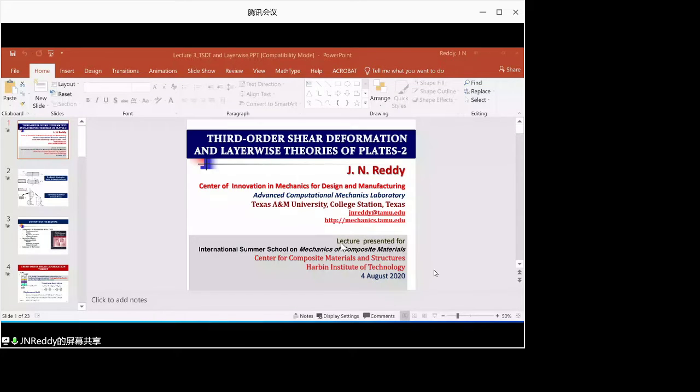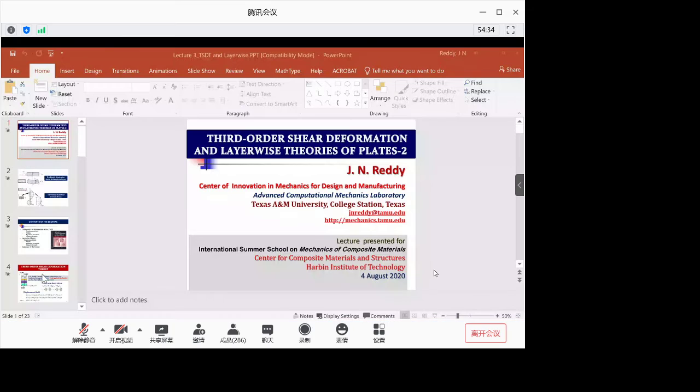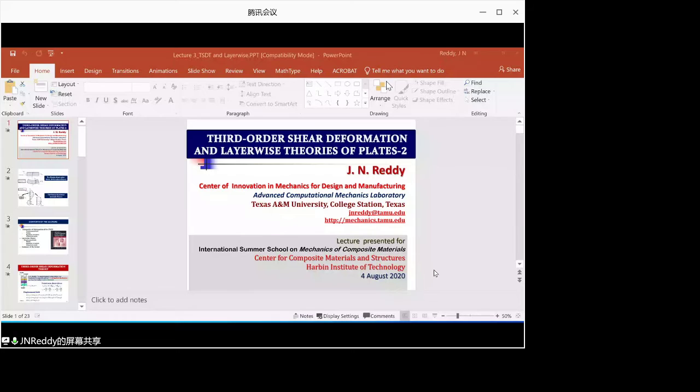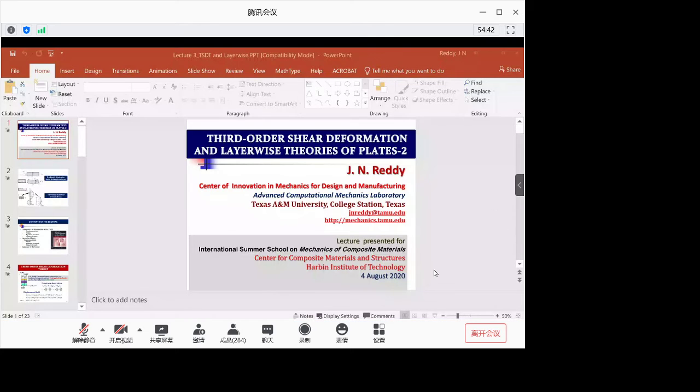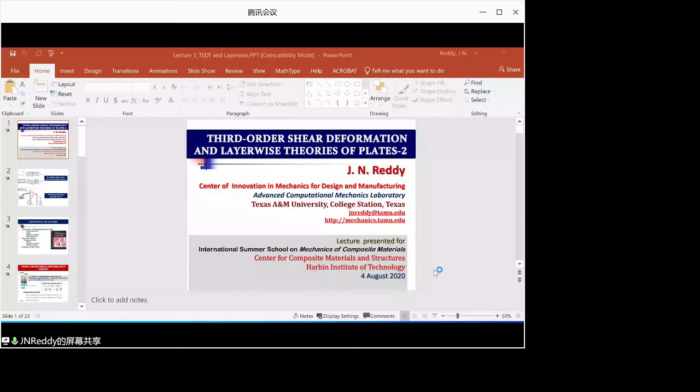The accuracy here is connected to the type of stresses involved. If you think of a three-dimensional state of stress in some places, especially around stiffeners or around holes, in those regions refining the mesh does not do the job because it still doesn't have the mechanism. So you have to use 3D element technology.